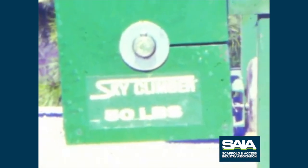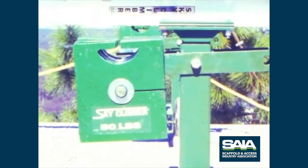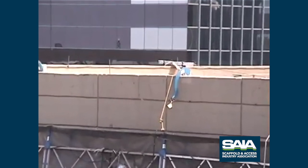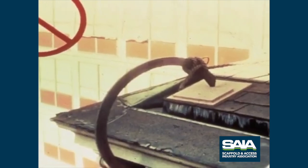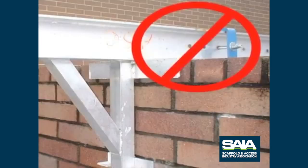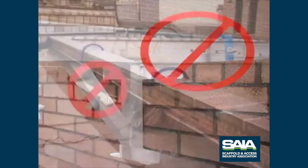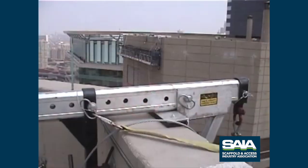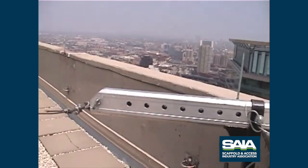Counterweights should be marked to indicate their weight. They must be secured to the beam as per the manufacturer's instructions. If a parapet is structurally sound, a parapet hook or clamp may provide a useful solution. Check with the building owner. These are examples of improper parapet hook and parapet clamp usage. Here is a properly installed parapet clamp, tied back and blocked for bearing.